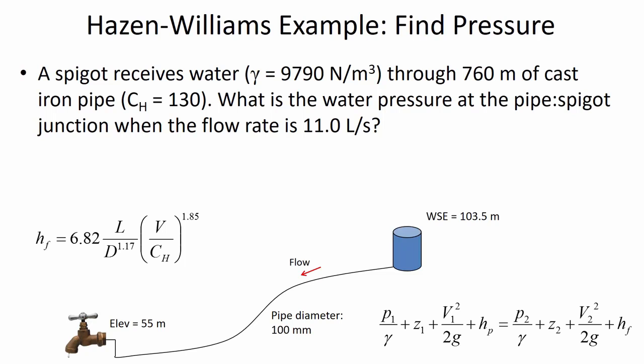And so suddenly you're just losing pressure, and the elevation didn't change, and the velocity on one side of the pipe is the same as on the other side of this valve, and so it's literally like a local loss where you're losing all of the remaining pressure head as the water flows through that valve. And so if you draw the EGL for when the valve is partly closed, then it would be a sudden drop.